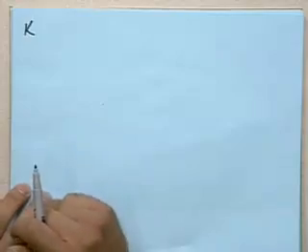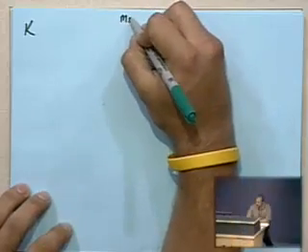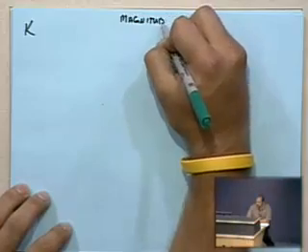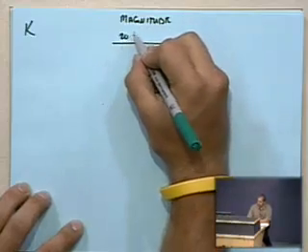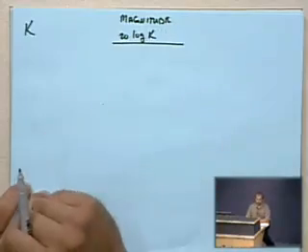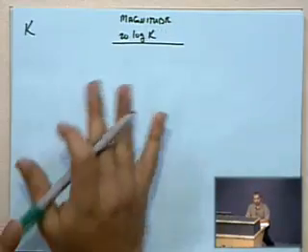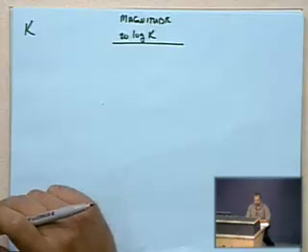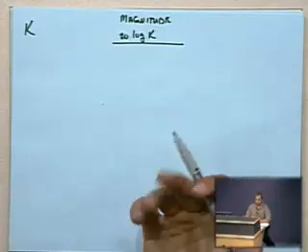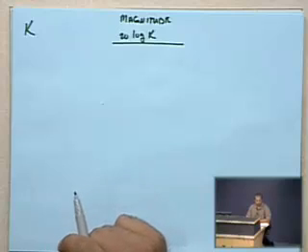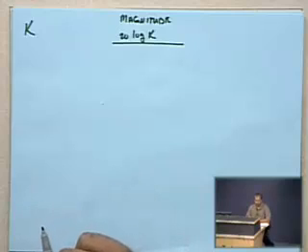So, the things that we had talked about that are very straightforward are, let's see, if you have a constant k term, the Bode magnitude plot of that is just going to be a straight line of the value 20 log base 10 of k. That's pretty straightforward, nothing weird there, and that's not different from what I had mentioned before. For what it's worth, the phase plot is a flat line at 0 degrees, but we're primarily concerned about magnitude plots, so I'm not going to worry about the phase plots too much.